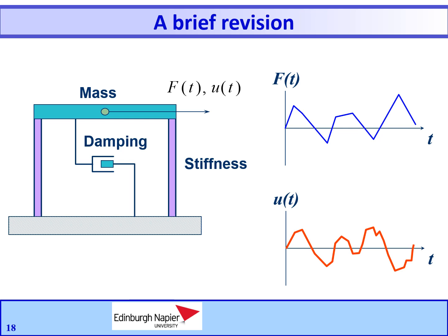This system may be considered as an idealization of a one-story structure. Each structural member, beams, columns, or walls of the actual structure contributes to the inertial, elastic, and energy dissipation properties of the structure. In the idealized system, however, each of these properties is concentrated in three separate pure components: the mass component, the stiffness component, and the damping component.